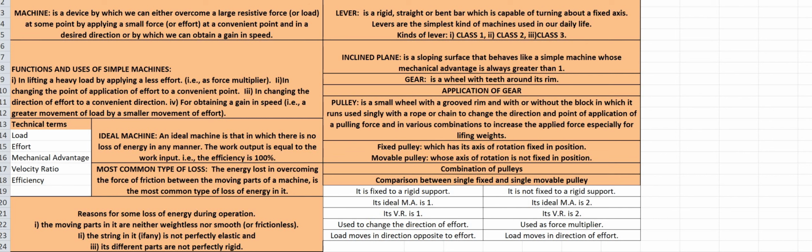The second arm of the gear attached to the shaft measures the time in seconds, so it takes one complete rotation in 60 seconds. If it has 120 teeth, the time period of the pendulum rotating it is kept at 0.5 seconds. This wheel is connected to the other wheel B with gear ratio NA by NB, which is equal to 1 by 60, and the minute arm is attached to the shaft of the second wheel B so that it moves one tooth corresponding to one rotation of the wheel A of the second arm.